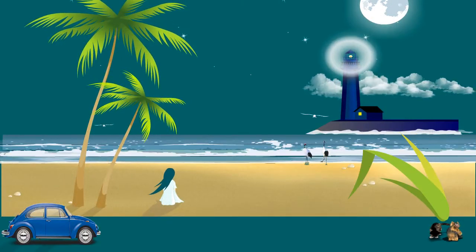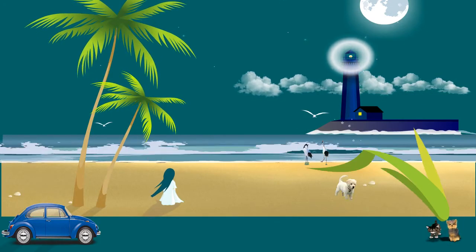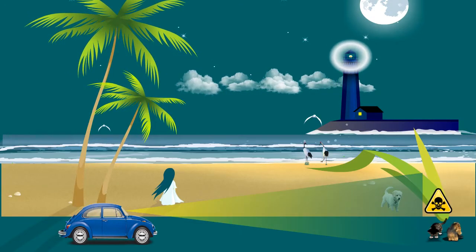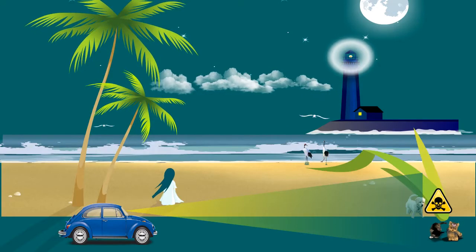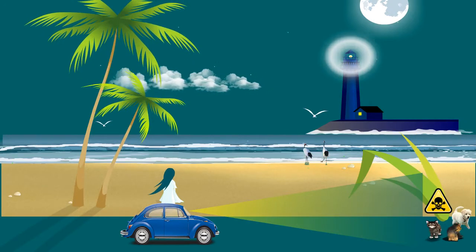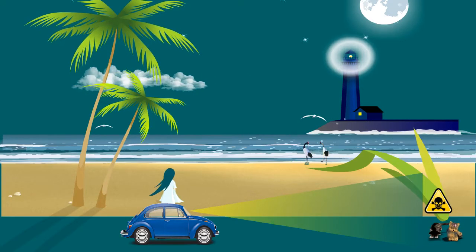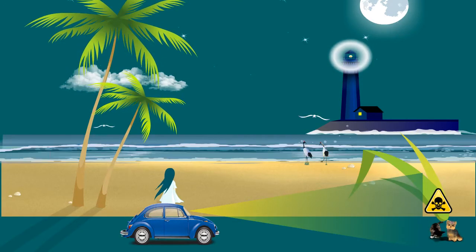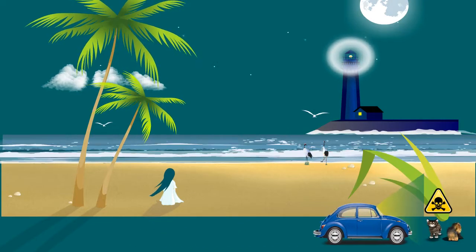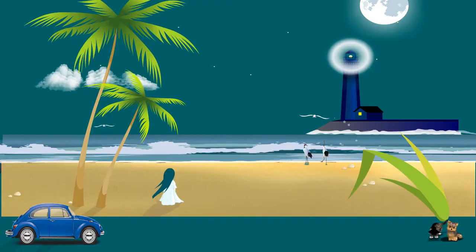Now, let us see what sight distance is, and why it is considered important in designing. While a vehicle is traveling on the road at a design speed, and some hazard is found on the road, the driver needs some time to observe the object and to react to it. And once the brake is applied, it will take some time to stop the vehicle, based on the deceleration of that vehicle's speed. Within this time, the vehicle will travel some distance based on the speed. The safe traveling distance between the vehicle and the hazard object is known as the stopping sight distance.